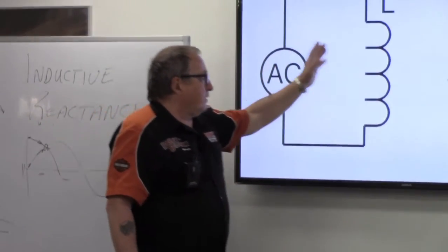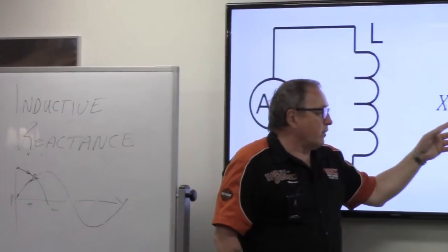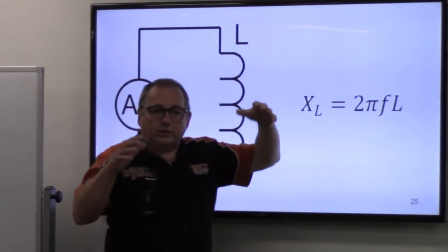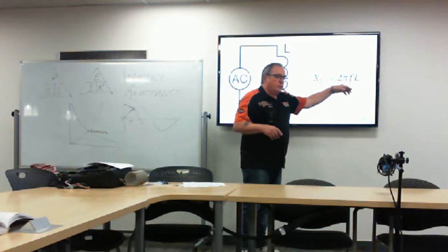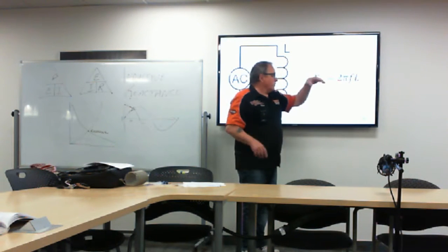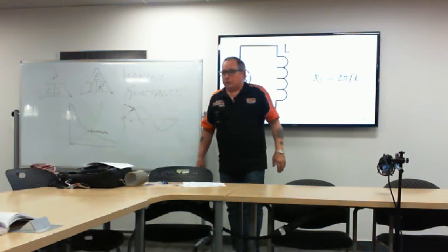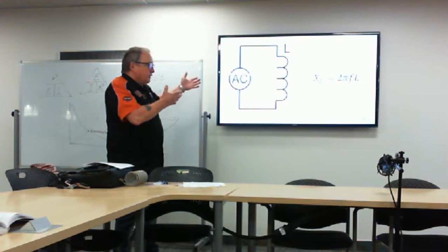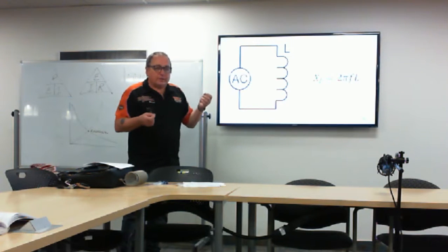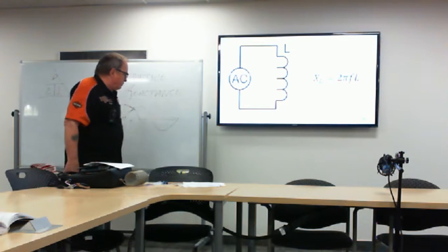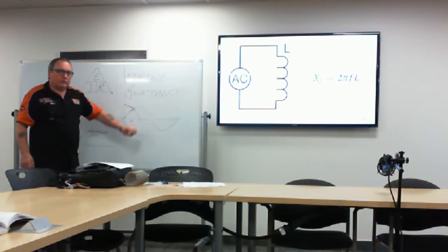In the inductive circuit, the inductive reactance, if you increase the frequency, the inductive reactance gets larger. If you increase the henries, the inductive reactance gets larger, and if you reduce them, they get smaller. So in our resonant circuit, you can see that's what we're tuning. We're tuning that reactance till we get to the point where these two come together.